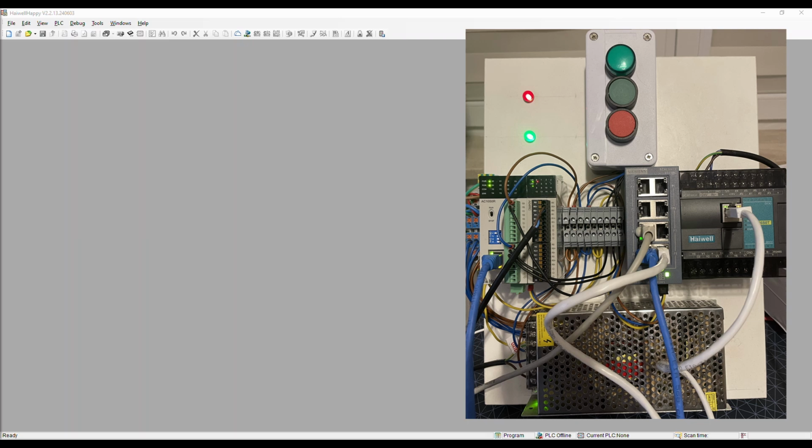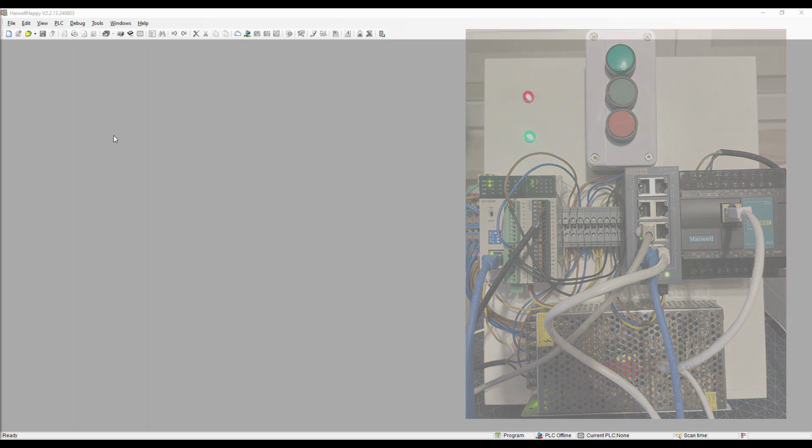AC series PLC is going to have an RTD temperature sensor and some push buttons connected to it. The engineering value of temperature that is connected to the AC series will be transferred to the T series PLC via Ethernet using a Haiwellbus protocol. Temperature will be sent only if the push button in the AC series PLC is pressed.